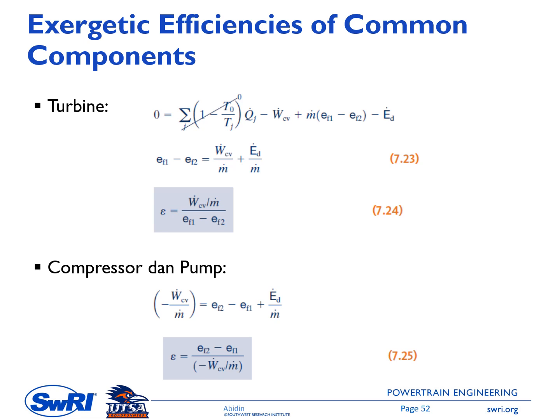From the exergy rate balance of the open system, in this case the turbine, we have this equation. On the left side, we have 0 because it's steady state. And in this case, we assume that the turbine operates under adiabatic conditions, so there is no heat transfer from the turbine to the environment. So Q is 0. And then for sure, the turbine will generate power.